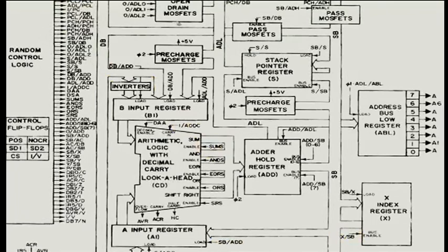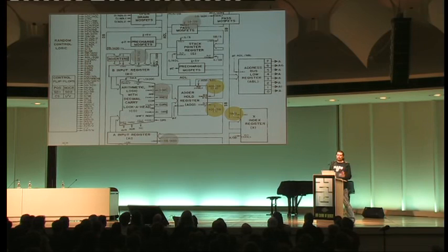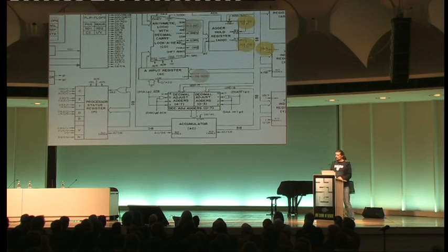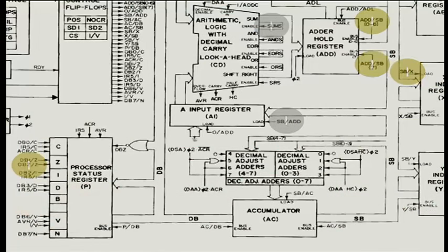Then in the second cycle, we have to get the add or hold register output, put it onto the S bus with these two control lines, and we store it into X in there. There are a few more bogus junk control lines there to keep the ALU occupied, which are a side effect of the way everything is encoded, and the way don't care works. So this doesn't have any influence on what's actually going on. But there are two more lines that are asserted: the one that sets the 0 flag, and the other one that sets the negative flag from the output.